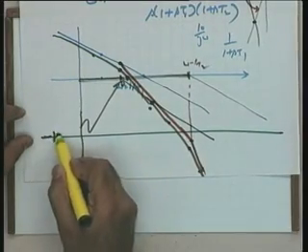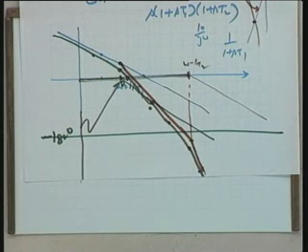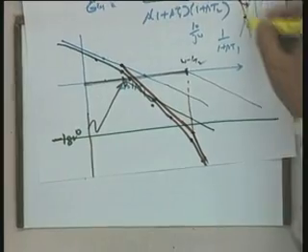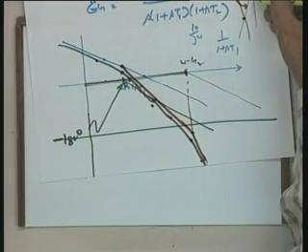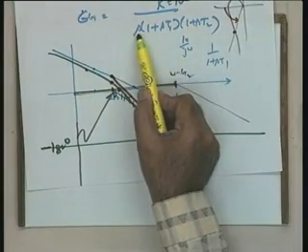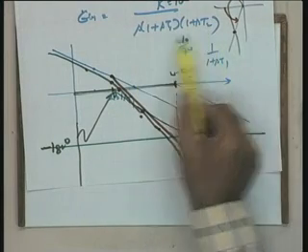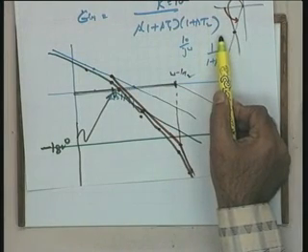If I draw a Bode plot right here, this is the minus 180 degrees line. I am now making a phase angle plot. In this particular case, what is the total phase angle range? Can I say that it will be minus 90 to minus 270? It is visible from the polar plot. Otherwise, for omega tending to 0 it is minus 90, and for omega tending to infinity it is minus 270. It is very clear from here.